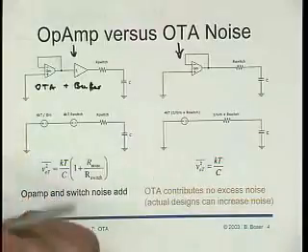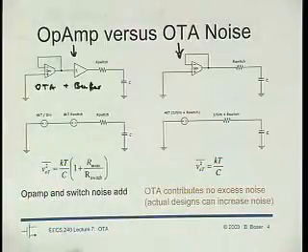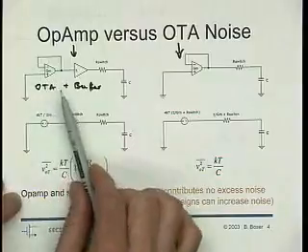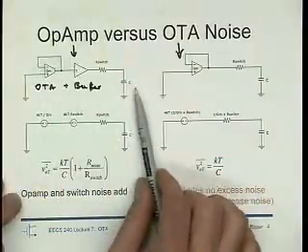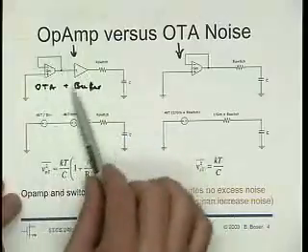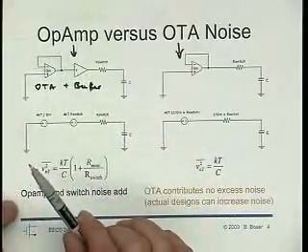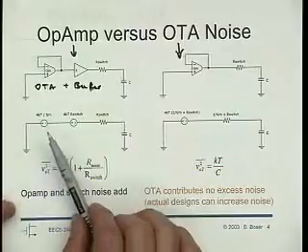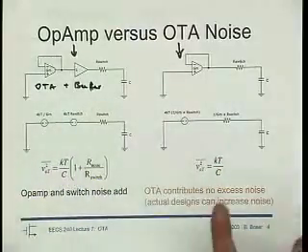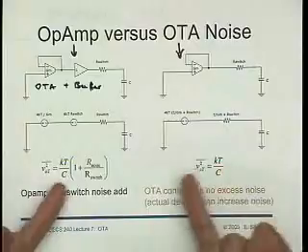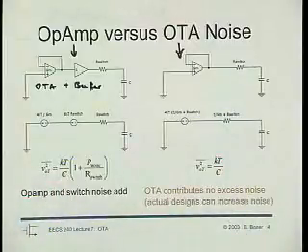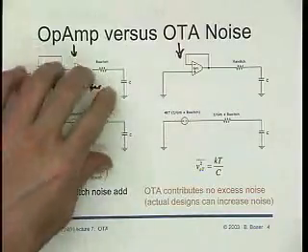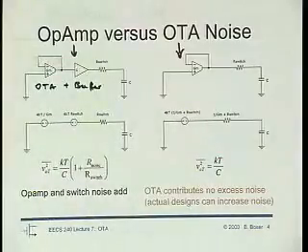We'll see that later when we analyze two-stage amplifiers. In that case the noise also is not kT/C_L, but kT over whatever capacitor actually determines the bandwidth of the system. So the comparison is not so obvious anymore because we have different C's here. But generally, because we have more components here, there is hardly a noise advantage in building an operational amplifier.